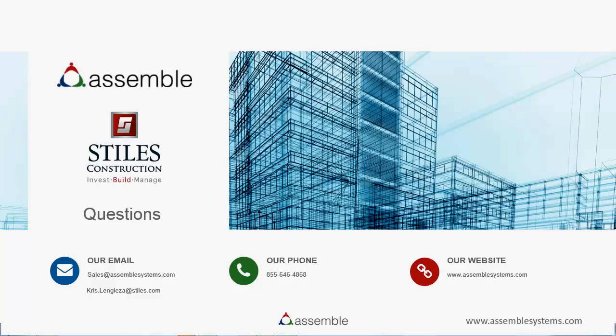As Chris was mentioning earlier, with shared parameters, or sorry, project parameters anyhow, you have to create those in Revit, and then if you get new versions of a model, you have to synchronize those back and then publish them again. But with Assemble properties, those will be persistent as you publish new versions of a model. So if I associate a cost code or something of that sort to model components, then every time I publish a new version of that model, I will be bringing those data sets forward.